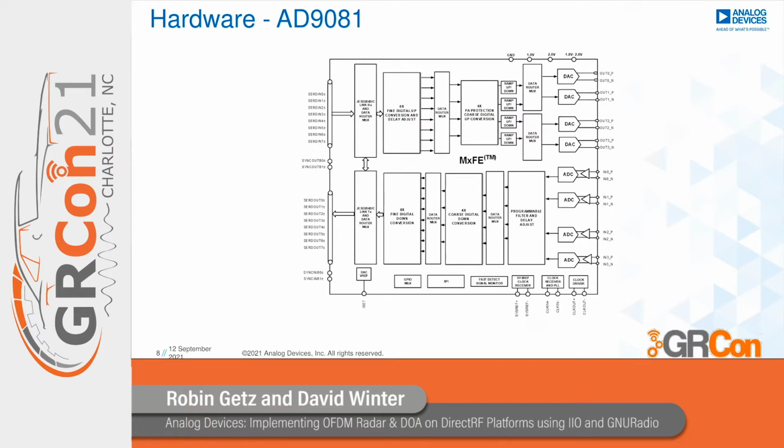And I don't really want to run a 2.4 gigahertz numerically controlled oscillator in my FPGA fabric. So all of that is available inside of the AD9081, it just needs to be configured, and what you get out of the JESD lanes are your downsampled sample streams at baseband.